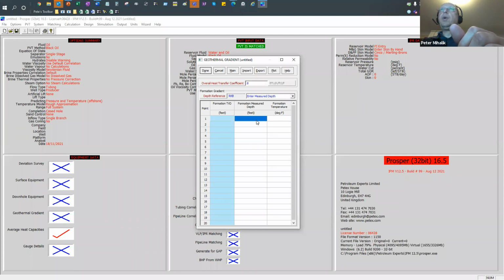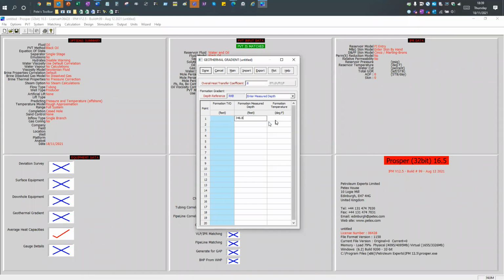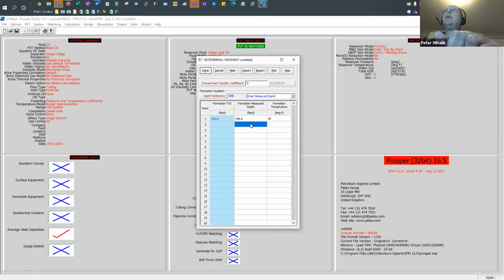Oh, actually, going to be modeling from the wellhead. Okay, so from the wellhead, which is at 347.8 feet, the temperature is actually going to be 40 Fahrenheit, which is kind of temperature at the bottom of the sea. This is your ambient temperature outside of your wellhead, and the reservoir temperature is 215.9 Fahrenheit. With that should be Control V, and this is the depth 8691.